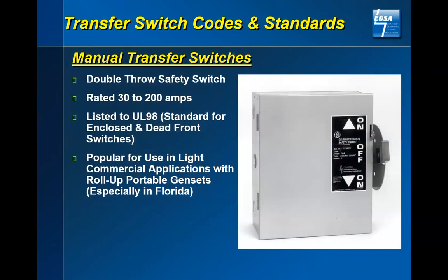A manual throw transfer switch. This is what I'm referring to. If you look at that, this is what typically had been specified as a manual transfer switch. When you look into your electrical components, this is actually a safety switch. Now, that safety switch can either be fused or non-fused, and it is rated from 30 amp up to 200 amp. You'll notice this one now is listed under UL 98. You can use it, but again, it's not acceptable in an emergency condition.